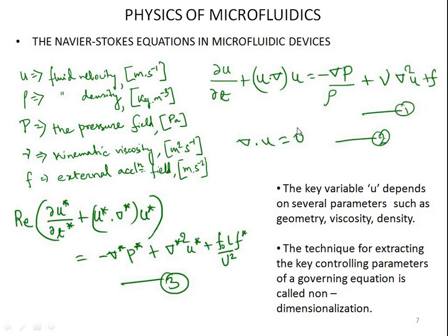So in microfluidics what happens is that our convective forces become least important in comparison to the diffusive forces, the molecular transport forces. So we basically focus on these molecular transport forces in microfluidics, where our inertia forces are least important and surface forces are more important. As we can see, it's a non-dimensionalized Navier-Stokes equation. Why we need non-dimensionalization, we will come to it in our subsequent slides.